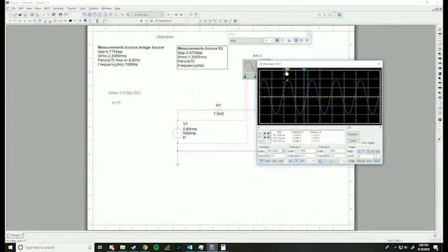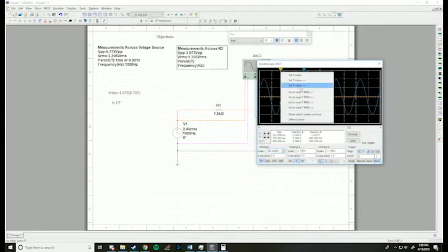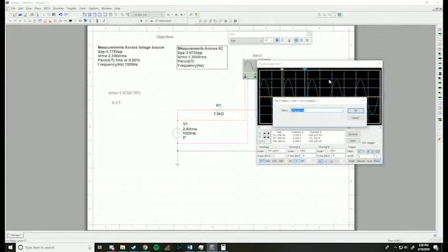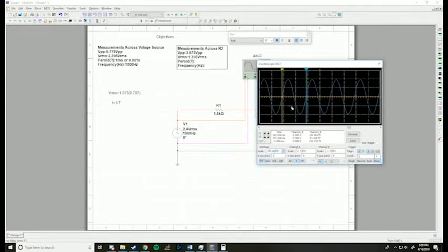And the period, it's the same method as last time. Let's go from the 0 right here, then to the 0 right here. And that gives us, obviously we're going to use absolute value here, but if you switch these around, it would be positive 1 millisecond. So that gives us 1 millisecond. And the formula is exactly the same. 1 divided by 0.001. And that's going to give us a frequency of 1000 hertz.